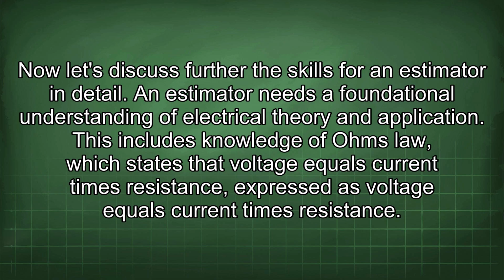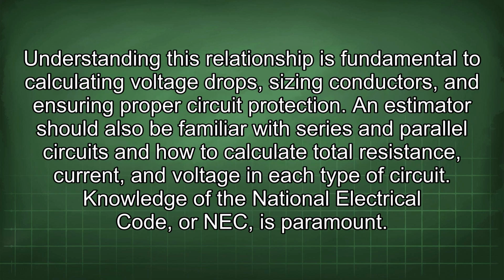This includes knowledge of Ohm's law, which states that voltage equals current times resistance. Understanding this relationship is fundamental to calculating voltage drops, sizing conductors, and ensuring proper circuit protection. An estimator should also be familiar with series and parallel circuits and how to calculate total resistance, current, and voltage in each type of circuit.